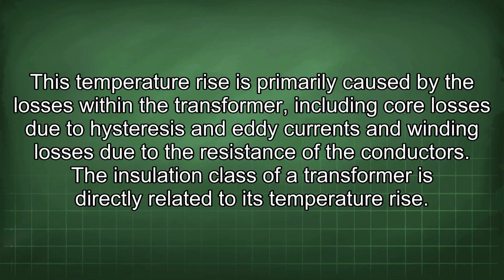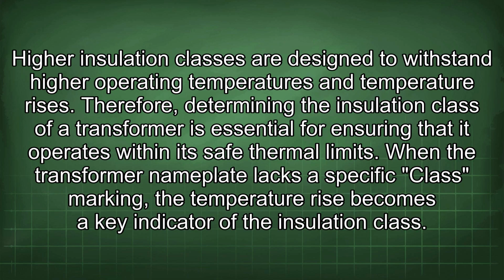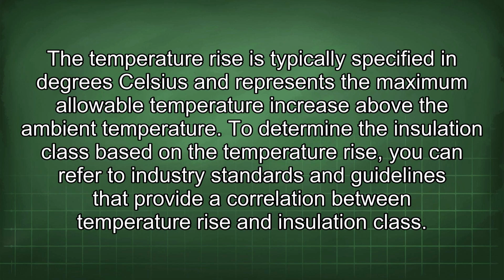The insulation class of a transformer is directly related to its temperature rise. Higher insulation classes are designed to withstand higher operating temperatures and temperature rises. Therefore, determining the insulation class of a transformer is essential for ensuring that it operates within its safe thermal limits. When the transformer nameplate lacks a specific class marking, the temperature rise becomes a key indicator of the insulation class. The temperature rise is typically specified in degrees Celsius and represents the maximum allowable temperature increase above the ambient temperature.